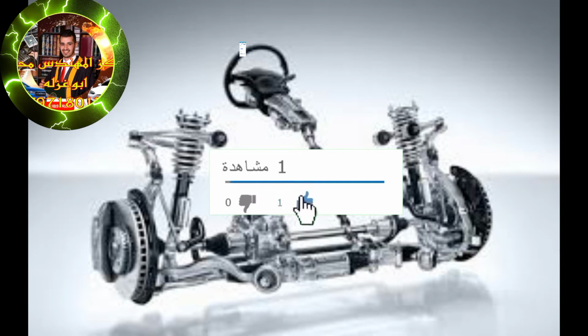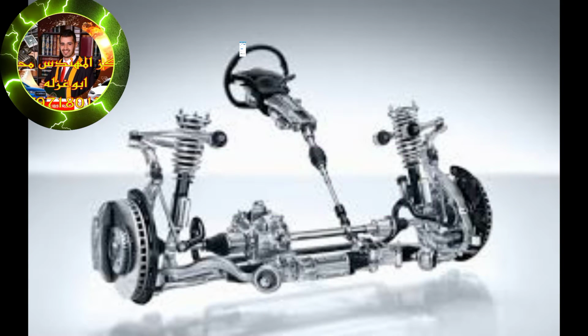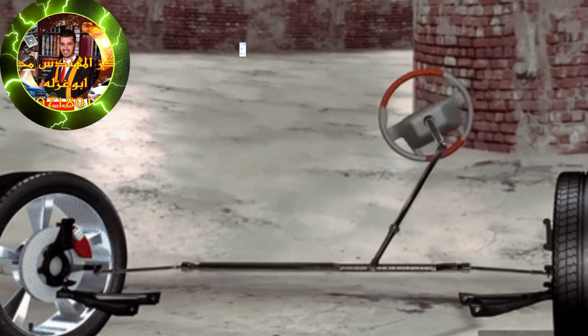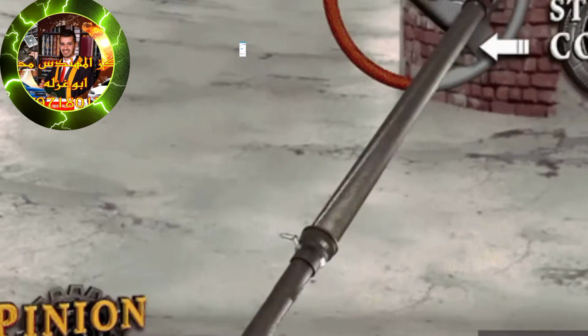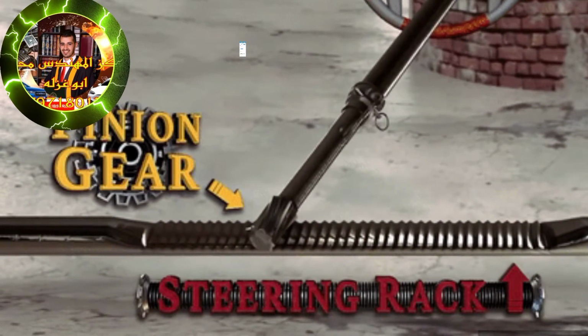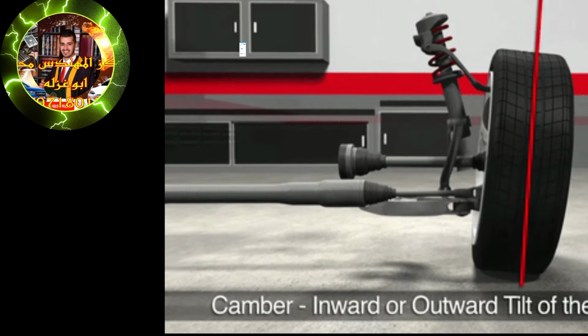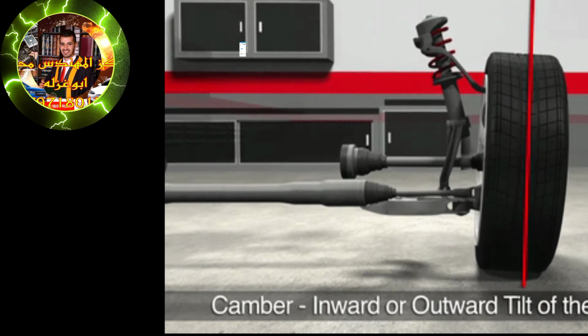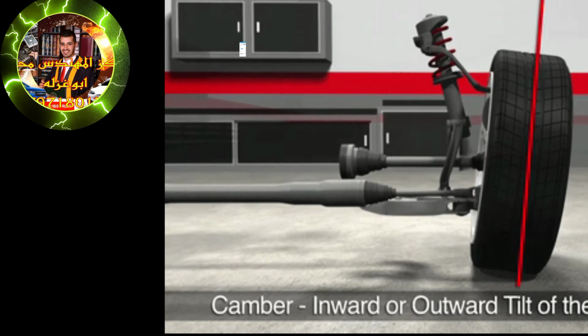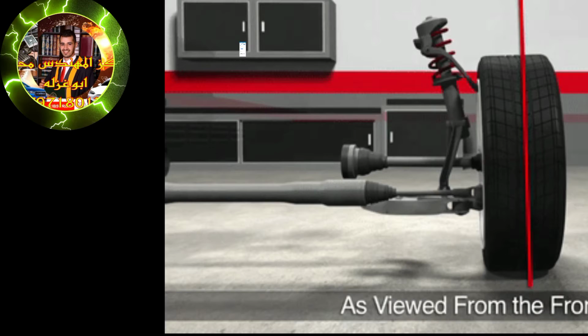8. Power steering. Optional. Many modern cars feature power steering, which assists the driver in turning the steering wheel. Power steering systems can be hydraulic or electric. Hydraulic power steering uses a hydraulic pump, fluid, and a series of valves to assist the driver's effort. Electric power steering uses an electric motor and sensors to provide assistance.